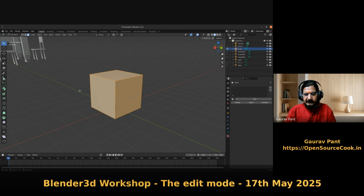First thing to do is that I am going to subdivide the faces of the cube. So I'll say subdivide. Now you see the first subdivide gives me 4 divisions, and this box comes up, and here we will do 2 subdivisions. It is giving me these many faces. That was my requirement. There are a few other aspects over here where you can move this to distort the shape and all. Fine, you can play around with that.